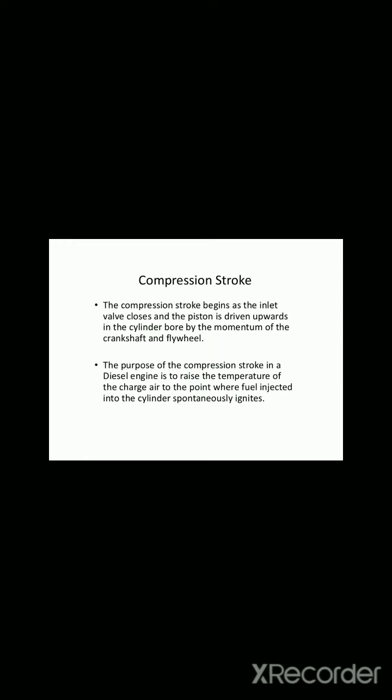Next point is the compression stroke. The compression stroke begins as the inlet valve closes and the piston is driven upwards in the cylinder bore by the momentum of the crankshaft and flywheel.